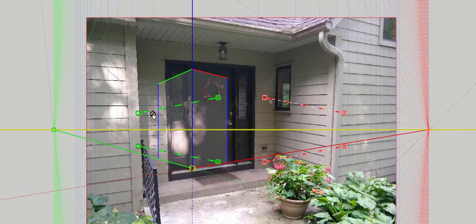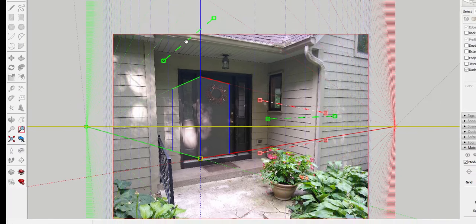Then I'll take and move these around. And the way I like to move them is by grabbing the middles first. If I grab the ends, I'll start changing the warping. I'd like to grab the middles and kind of put them in position. So I'm looking for places that go in the green axis, that vanish to this particular vanishing point. Well, these are all vanishing that way, right? So are these in the soffit here. So I'm just going to go ahead and click and drag this over to this side. And I'll click and drag this maybe up here, kind of like that. We'll start there. These may be a little too short, but we'll see.